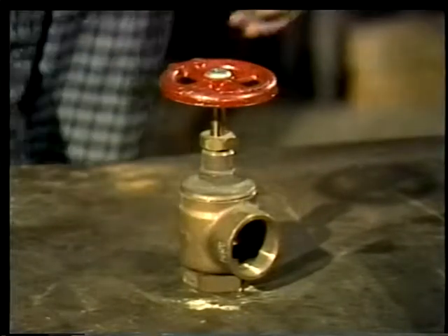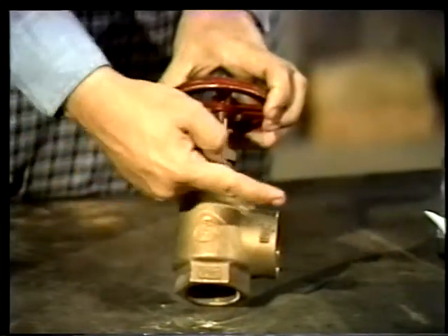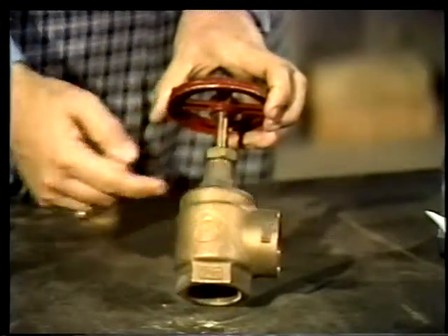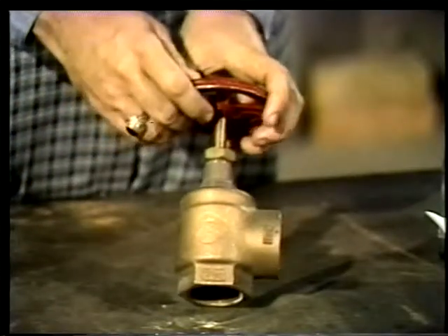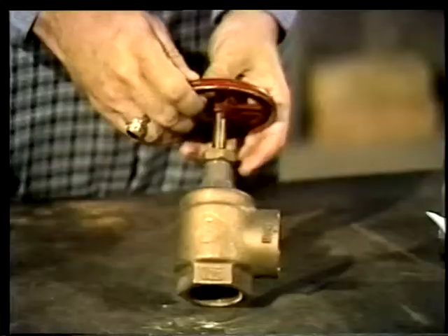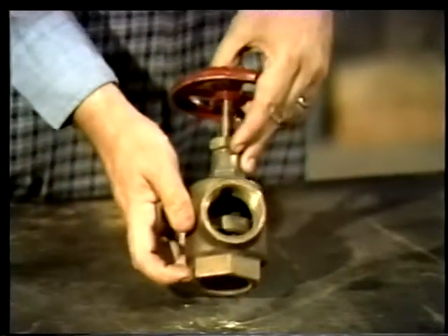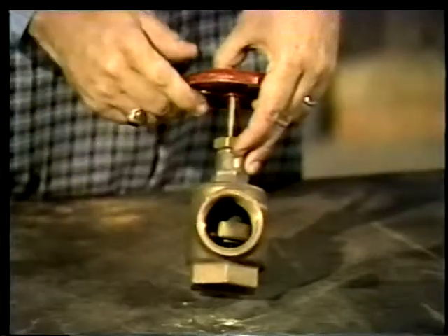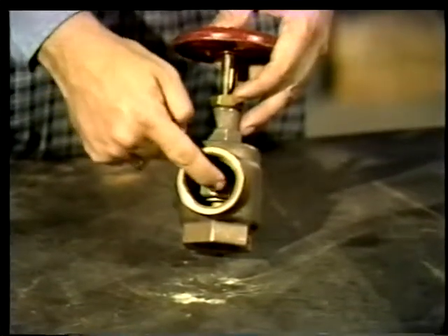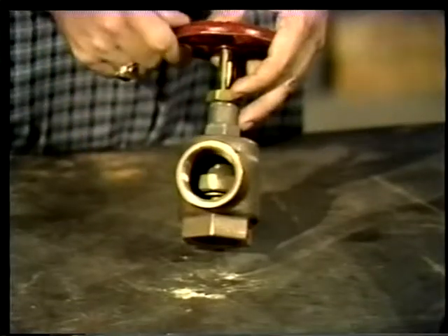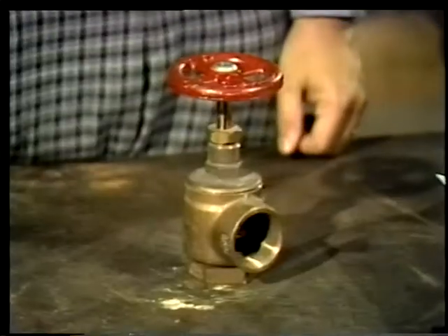Another body type is the angled globe valve. This design helps to eliminate the need for adding elbows to change the direction of flow, thus reducing the number of joints. The fewer number of joints, the fewer points leakage can occur. Now, both of these surfaces are built to provide a tighter seal for positive seating than is found on a typical gate valve. The shape and arrangement of the disc on a globe valve is varied depending on the type of service it's designed for.